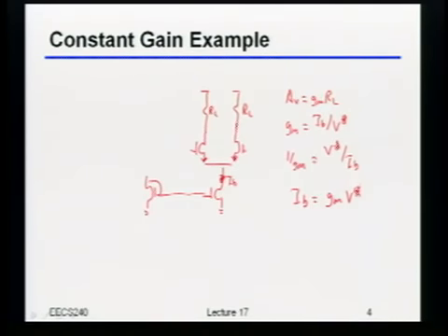You can put a resistance on the bias side. Okay. And what then do I put across that resistance? You can put a feedback loop and measure the voltage at the other end and tweak a current source. Okay, so by the way, what voltage do I want to appear across this resistor? Yeah, I want V star to show up across this resistor, right?